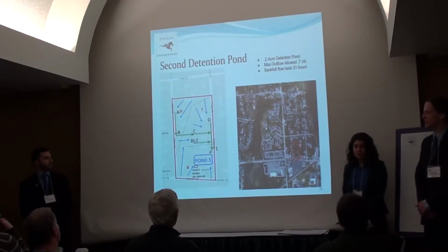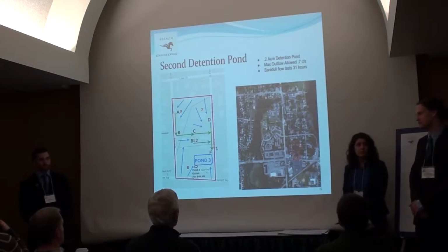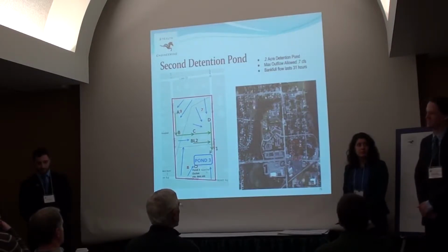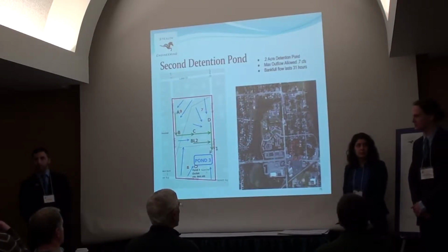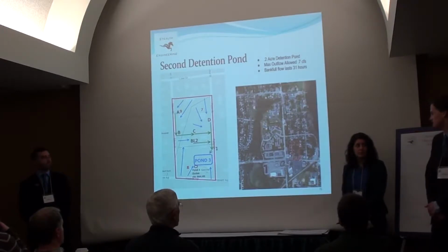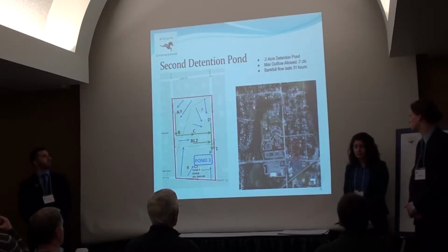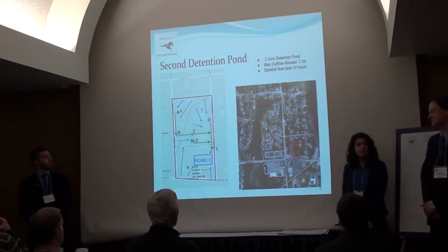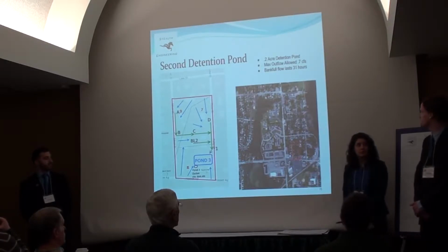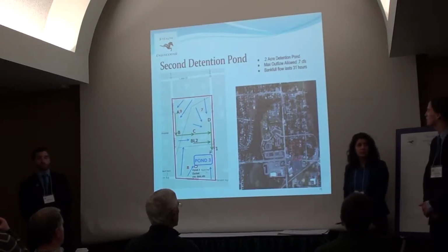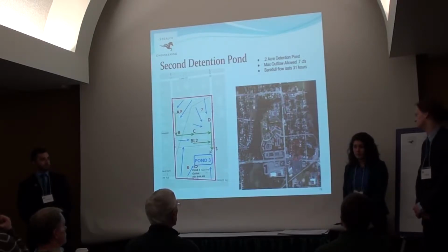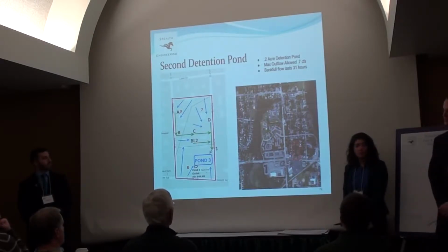With the 5 acres of land and the same regulations previously described, there's 0.7 outflow for pre-development, so we must meet this using the detention pond. And with the detention pond of 0.2 acres on the plot of land which is available for purchase that would fit on this plot, we were able to effectively route it down to 0.5 CFS, which meets regulations. We also did the bankful for this pond, and it took 31 hours, which also meets the 24-hour regulation.